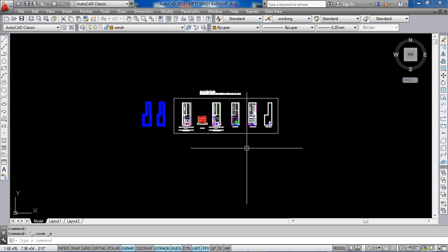In my view, the plan which has the maximum number of walls should be considered for making the single line plan, because for each wall we have to place a beam below it.